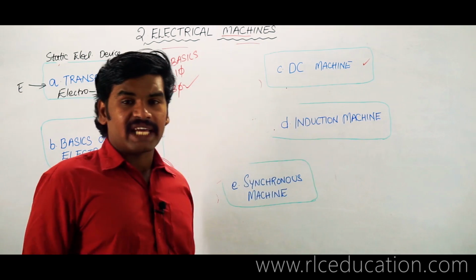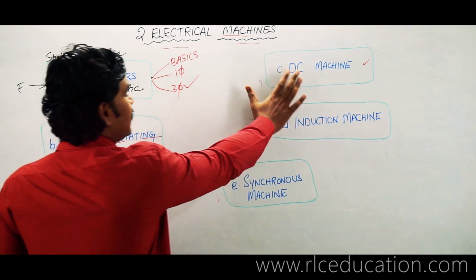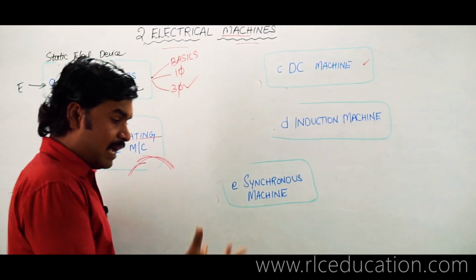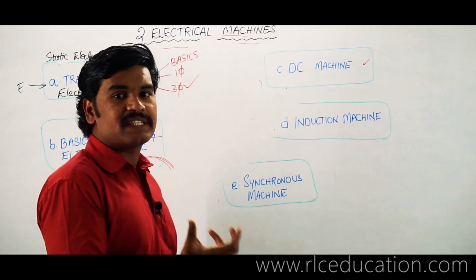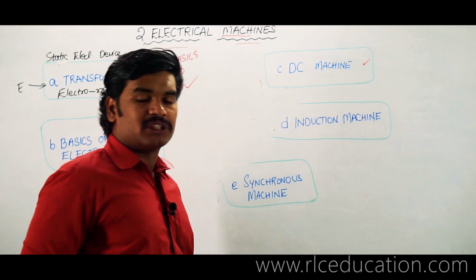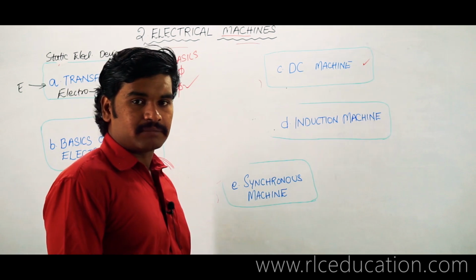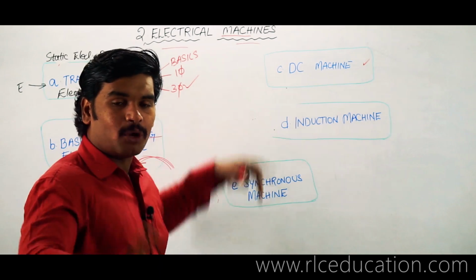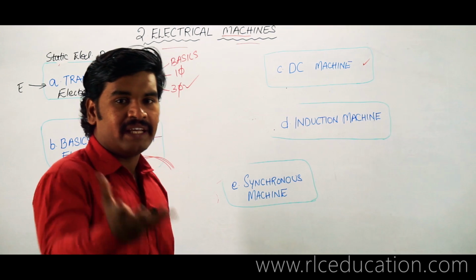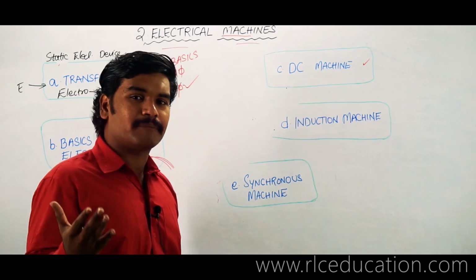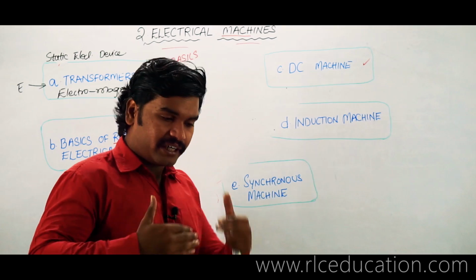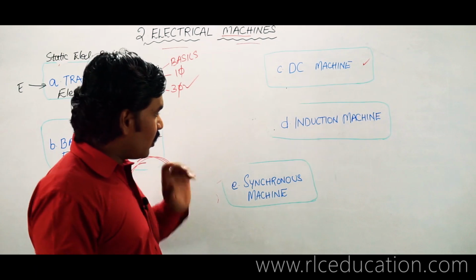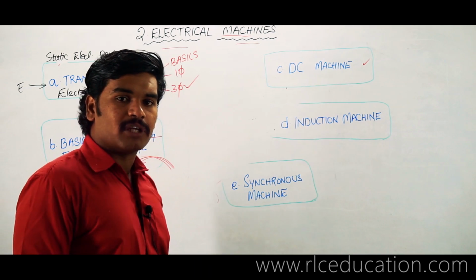Now what I exactly mean is, see, this is a machine. The machine requires an input stage and an output stage, which could be electrical or mechanical. And in between, the important aspect which makes the energy conversion possible from electrical to mechanical is the magnetic system. So you require a magnetic flux to be produced. Without magnetic flux, however much you rotate or whatever energy you apply, this conversion does not take place, isn't it? How does electrical energy directly convert into mechanical energy? It is obviously because of that magnetic system. So you have to provide the magnetic system also, isn't it?